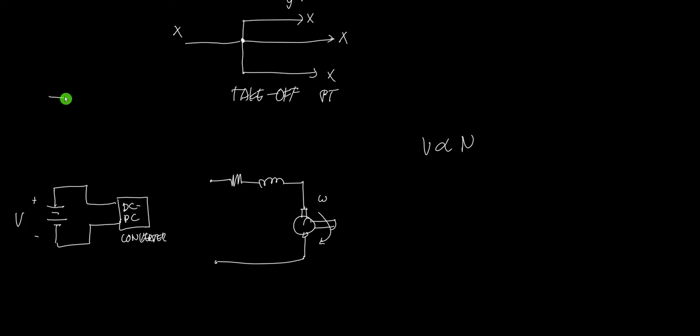So if we have a MOSFET somewhere here, a switch, then I have an inductor, then if this is a diode, then you have a capacitor, a filter here. So this is your V input here, and we have your V output here. So this one is an example of a buck converter, DC-DC converter. It steps down the input. So this is a buck.